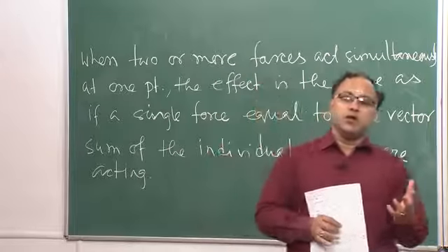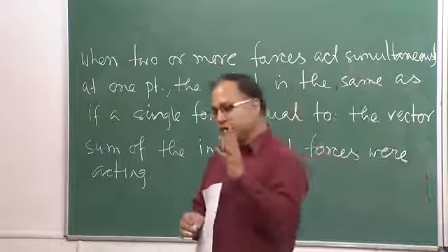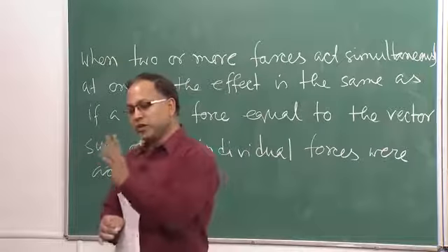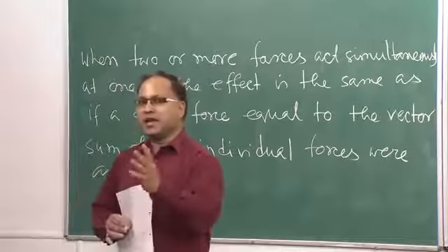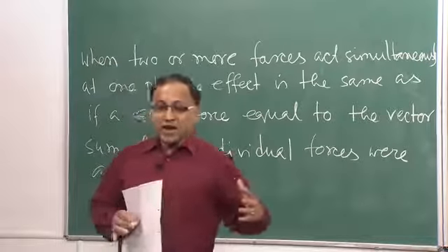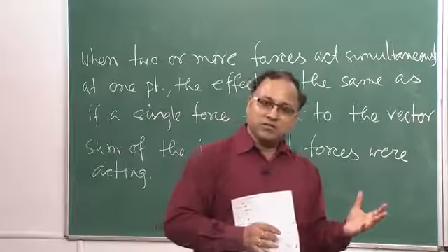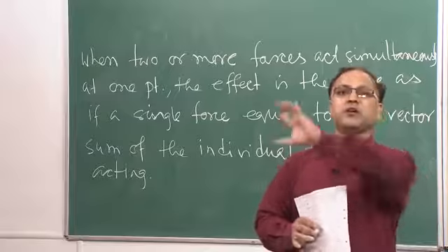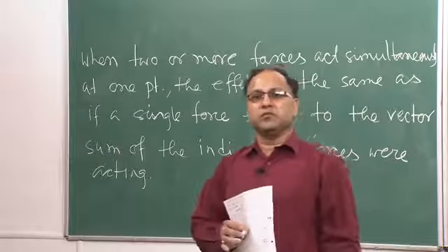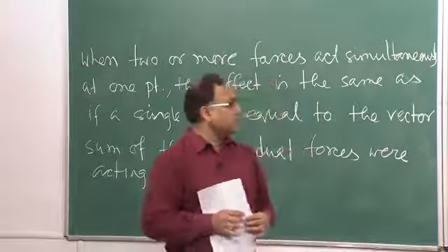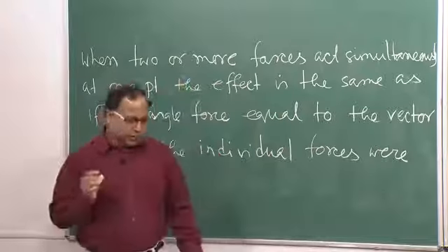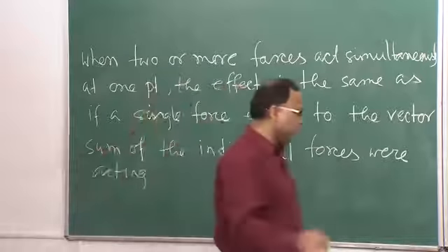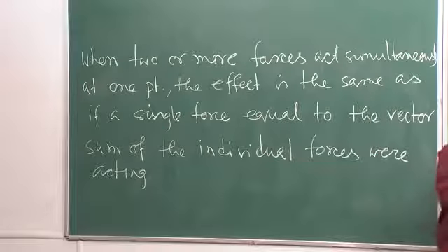So what you can do is apply individual forces and get the response, and you can add the responses together later on to get the total response from the complete simultaneous force system, right. So this method is known as the method of superposition. We will use this method later on, and you will appreciate that it is very, very handy.